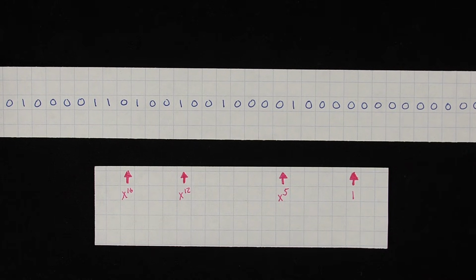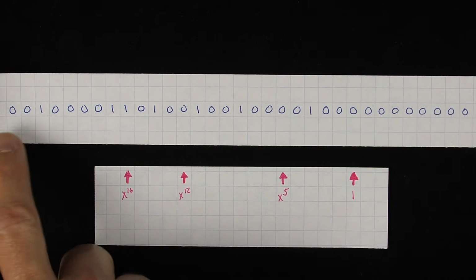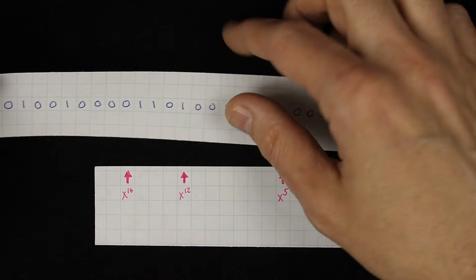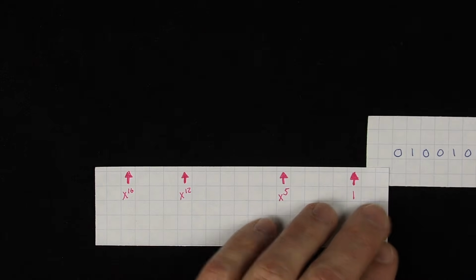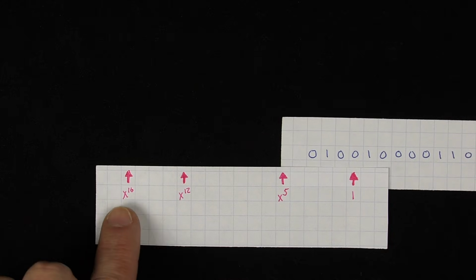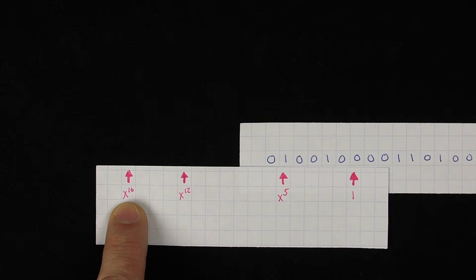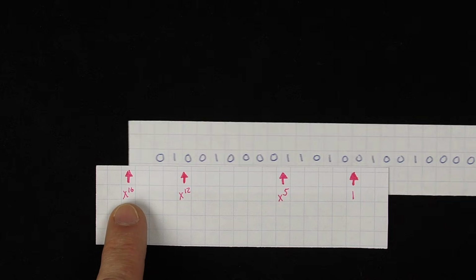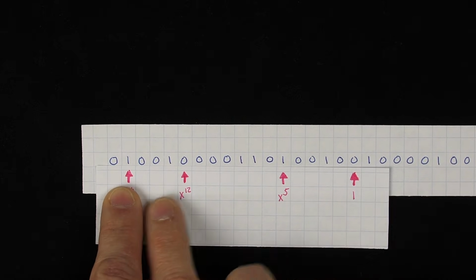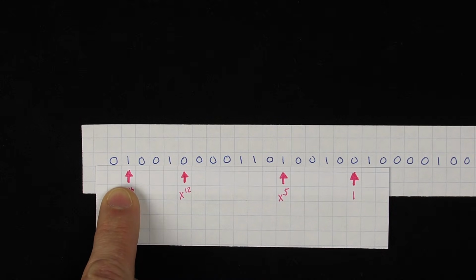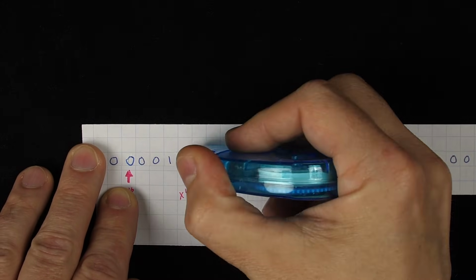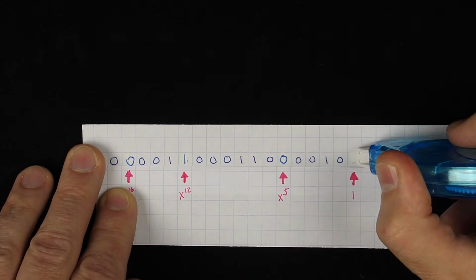So now let me show you that same mechanics of sliding and flipping represented a little bit differently. So here we have our message in binary, and then this is the generator polynomial. And another way we can think of it with that same sliding and flipping idea is we can slide our message along like this until the x to the 16th place lines up with a 1. And so we keep sliding and sliding. And so here we have a 0, and now it lines up with a 1. Okay, now that that lines up with a 1, what we can do is flip each of those 4 bit positions. So what I'll do is use a little whiteout here to flip each of those. So that becomes a 0, this becomes a 1, this becomes a 0, and this becomes a 1.